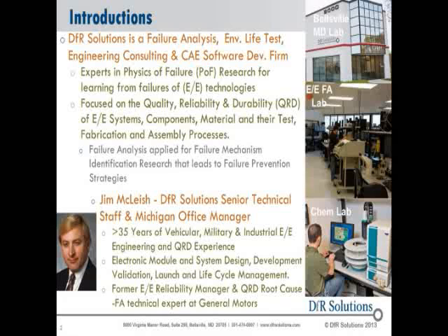We focus on a total approach to quality, reliability, and durability of EE systems, components, materials, as well as test methodologies applied to them and the fabrication and assembly processes. So for us, failure analysis is applied for failure mechanism identification research, and we use this knowledge to develop failure prevention strategies.